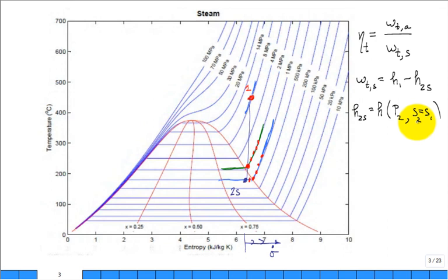All right. So what you do when you're given this piece of information, I like to, first of all, calculate H2S, then calculate the work of the turbine if it was isentropic, and then finally unravel to calculate the work that the turbine actually produces, which is a fraction. The efficiency is the fraction times WTS, if it had been isentropic.